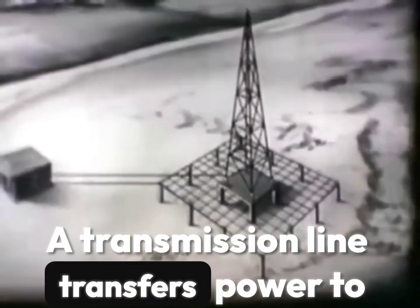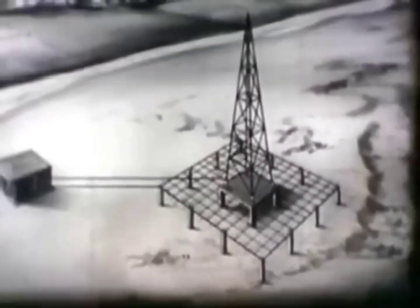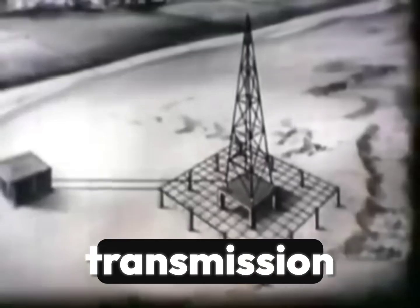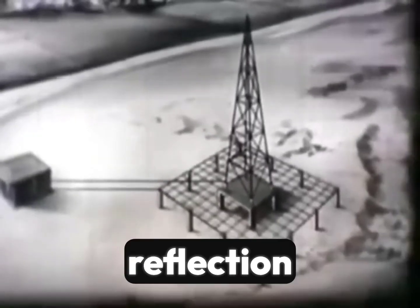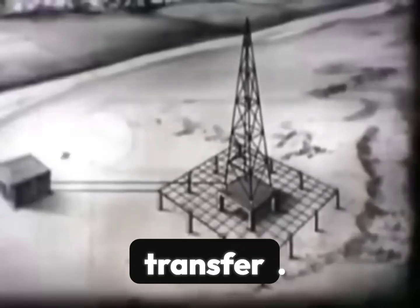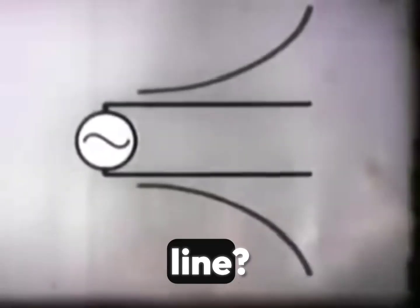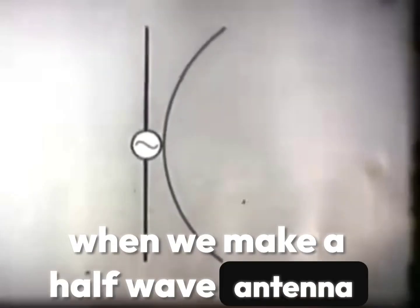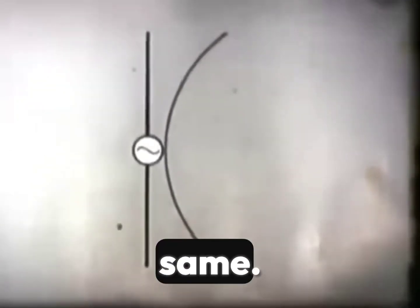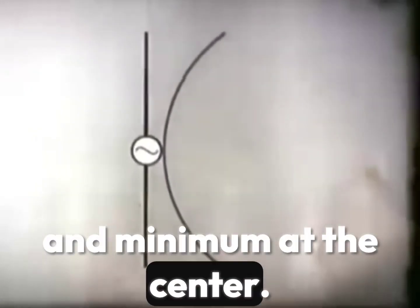A transmission line transfers power to the antenna, and herein lies a final problem: matching the impedance of the transmission line to the input impedance of the antenna in order to eliminate reflection and obtain maximum power transfer. Remember the impedance curve on our quarter-wave transmission line? Watch what happens to the impedance curve when we make a half-wave antenna out of this line. The general shape of the curve is the same. Impedance is still maximum at the ends of the line and minimum at the center.